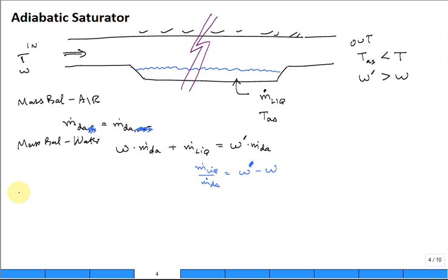The hardest one is the energy balance. Okay, this takes tediousness. It'll take a couple of pages. I'll have to work through it, but I'll try to do it as efficiently as possible. So on the inlet air, you have the mass flow rate of dry air coming in, and then you have the enthalpy, true, of that dry air coming in.